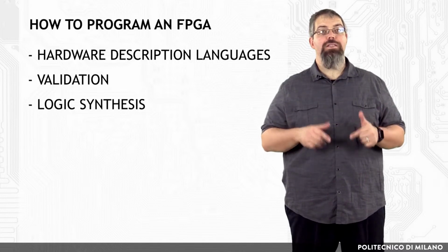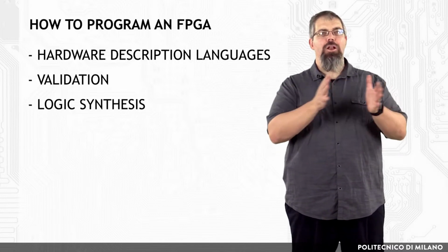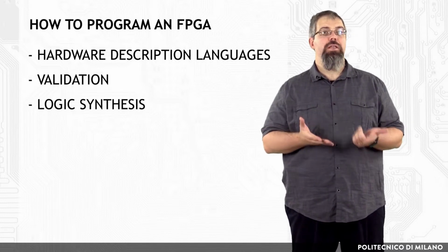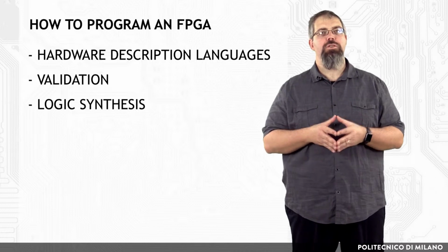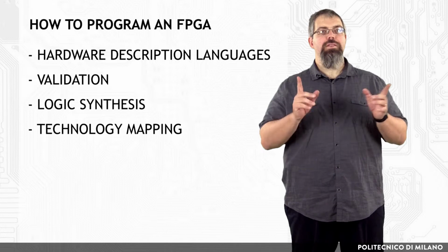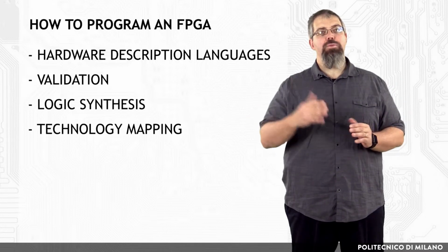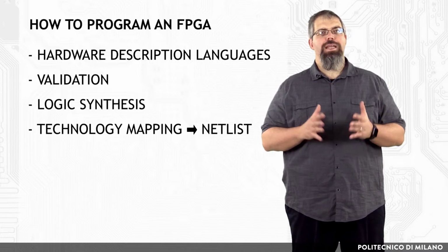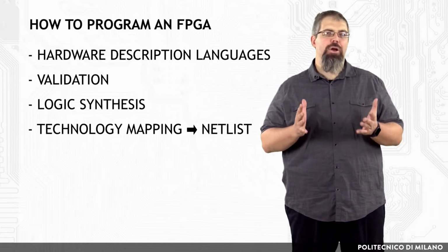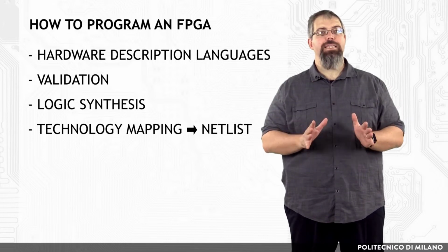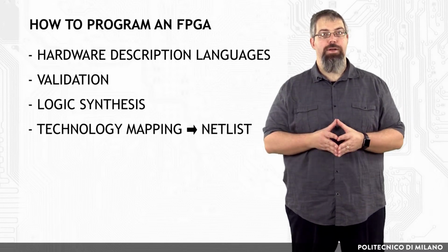What we are now interested in doing is mapping the logic gates and flip-flops we have onto the elements available in a specific technology, because of the FPGA chosen to implement our system. Because of this, the phase is called technology mapping. The output of the technology mapping phase is a netlist. Within this context, we can see technology mapping as the process of describing a circuit with a netlist that consists of only gates belonging to a specific technology library.